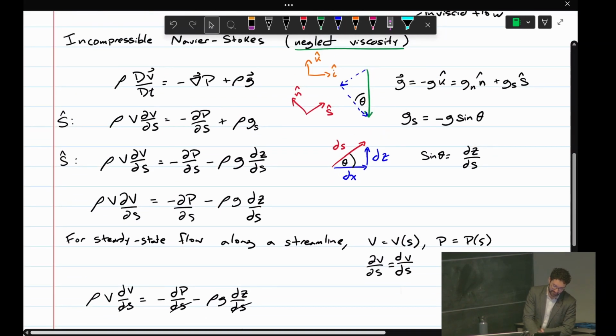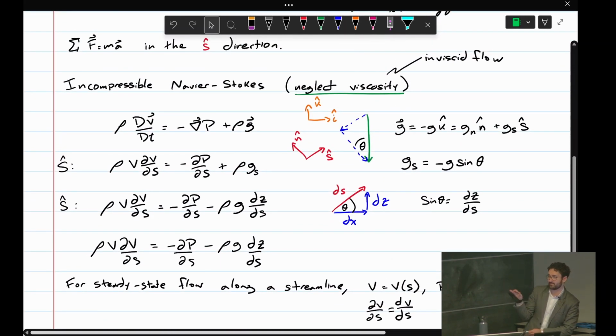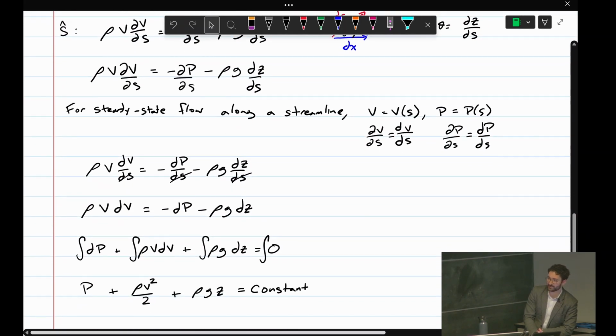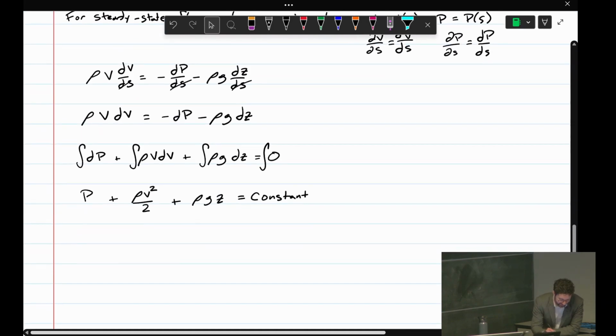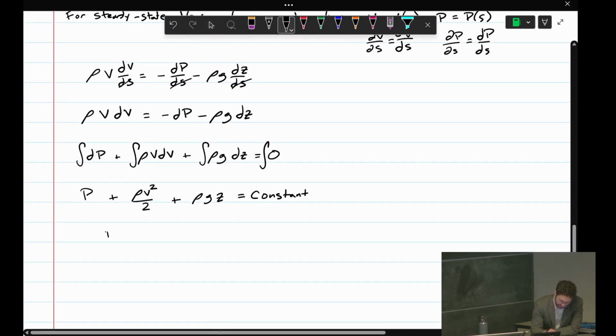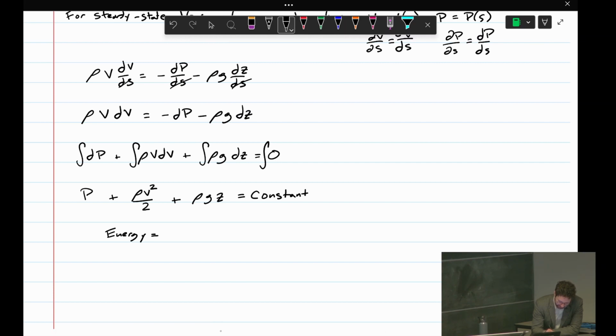We started with conservation of momentum and we integrated this along a path. If you go back and look at your notes, you might not have understood it at the time, but maybe you have more understanding now. If you go back and look at your kinematics and energy notes, that's basically how you derive the 1/2 mv squared plus mgy equals constant. So this is basically energy is constant. So total energy is constant along a streamline.